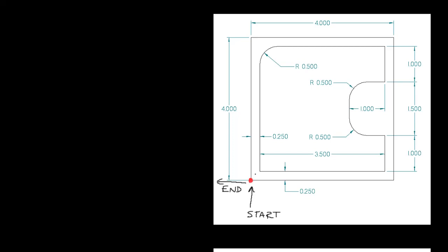Okay. And so I'm going to start, maybe over here. I'm going to start off the part and then come along here. So that'll be where I'm going to start. So I'm going to call that y is equal to -1.00. That's just going to be off the part in the y direction. So maybe I should specify that too. So the y is going to be going up, and the x is going to go in the horizontal direction.